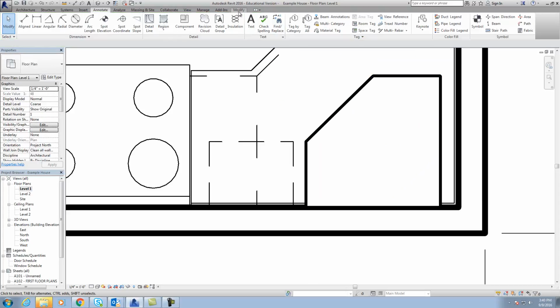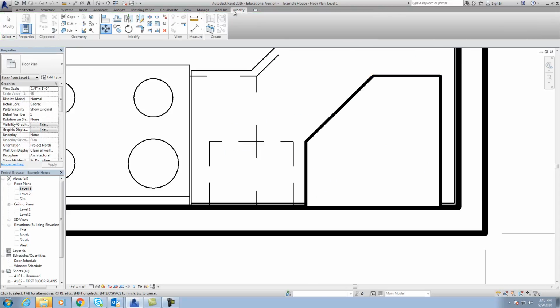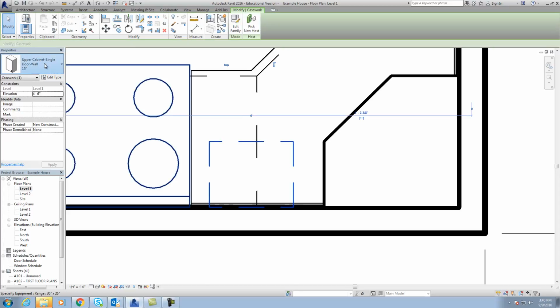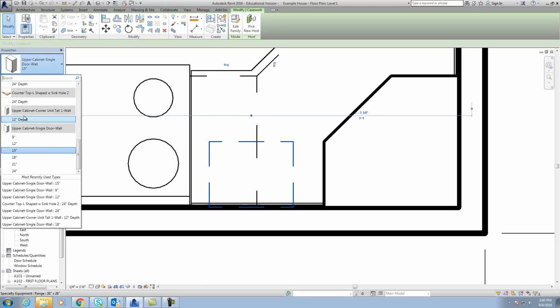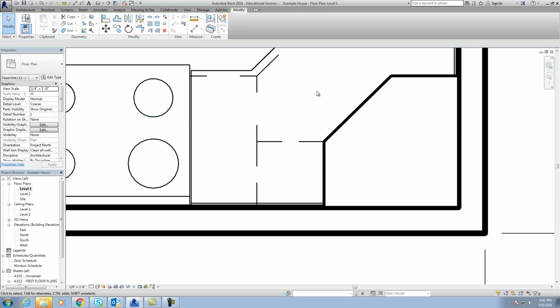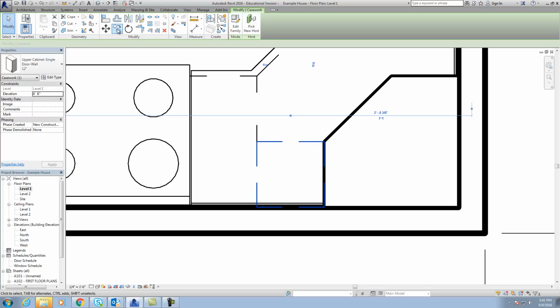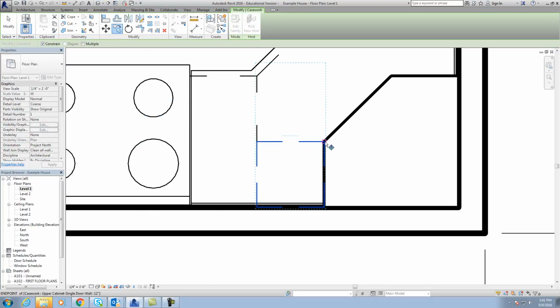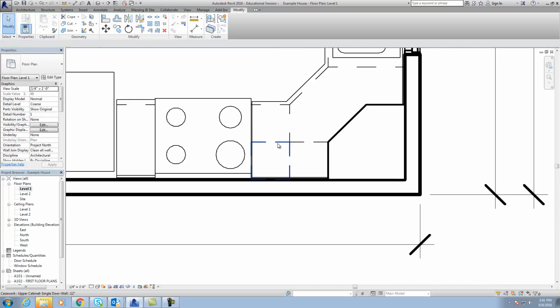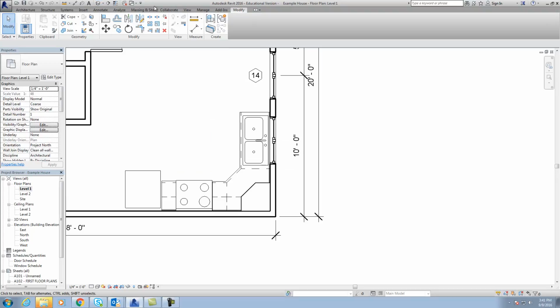And to check it, like I said, sometimes using that align button is the best thing you can do. Come over here and bring that over in there, and let's see if we can't get this thing lined out. Because we should be able to fit two 12-inch cabinets in that. Let's see what happens. Yeah, we can. Not a problem. That fits perfect. That looks better. And then I want to take this one and mirror image it right across this stove. That way it fits on the other side perfect where our doors are opening accurately.